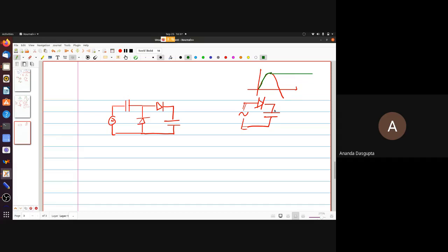Okay, but this is really no use as a rectifier at all, because a rectifier is meant to deliver power somewhere, so it's meant to deliver current. So you need to connect a load across it. But what this is good for is that this is a peak detector. It can just measure the peak value of whatever input voltage you're giving, right? Because now the voltage which it holds constant at is whatever constant maximum value you gave.